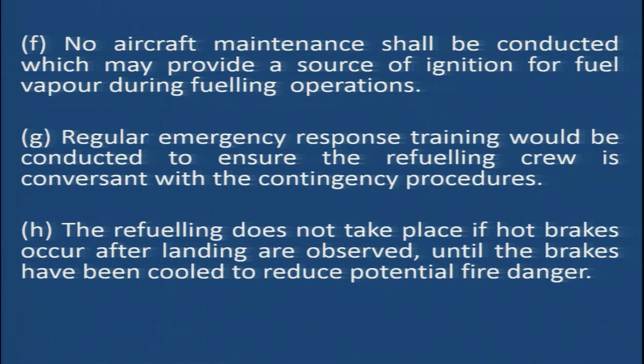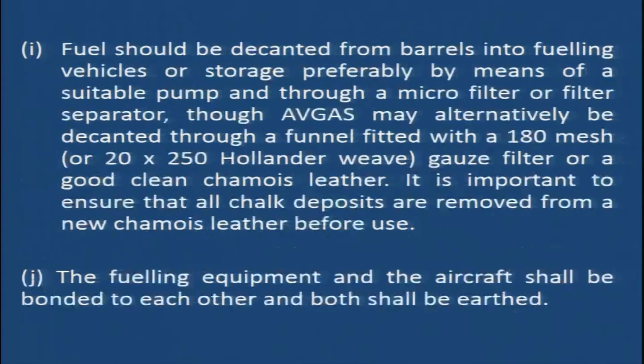Regular emergency response trainings should be conducted to ensure the refueling crew is conversant with the contingency procedures. Refueling does not take place if hot brakes occur after landing until the brakes have been cooled to reduce potential fire danger. So, some basic precautions: in case your aircraft has come with hot brakes, we need to wait till the brakes have cooled down and only then should the aircraft be refueled.